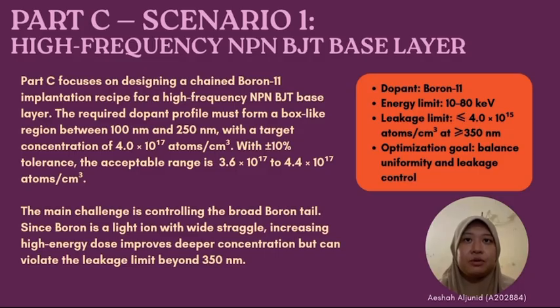For Part C, our science scenario is the design of a boron-11 implantation recipe for a high-frequency NPN-BJT base layer. The target doping region must be located between 100 and 250 nanometers below the silicon surface. The required target concentration is 4 times 10 to the power of 17 atoms per cubic centimeter.